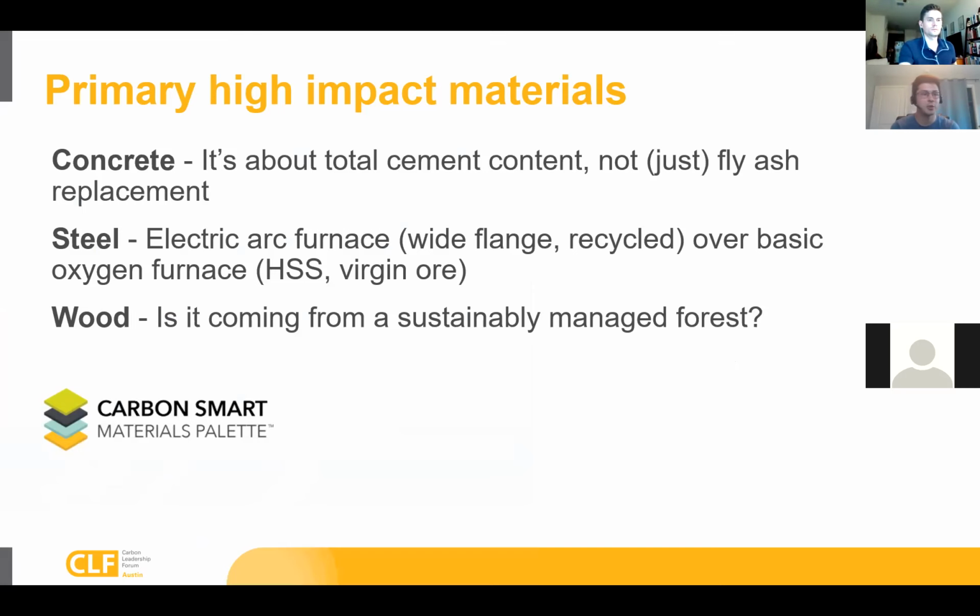If you have 500 pounds per cubic yard of cement, and then you have another mix that's 500 pounds per cubic yard of cement, but it has some fly ash, it might have higher SCM replacement, but it's going to have very similar impacts. The cement content's what's driving that. And there are different ways of getting there. So the SCM replacement is one way, but there's also being more intentional about your cure times. There's CO2 injection from stuff like CarbonCure.